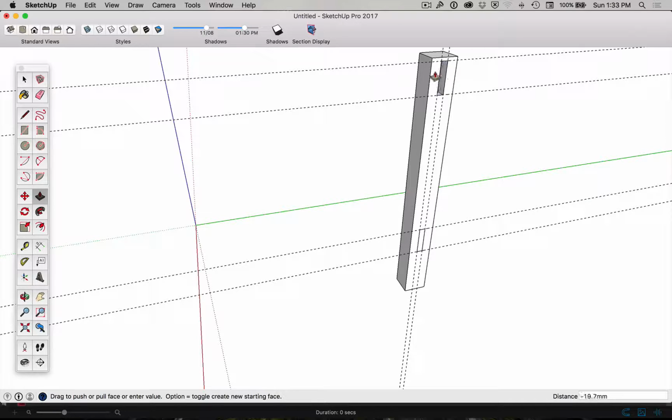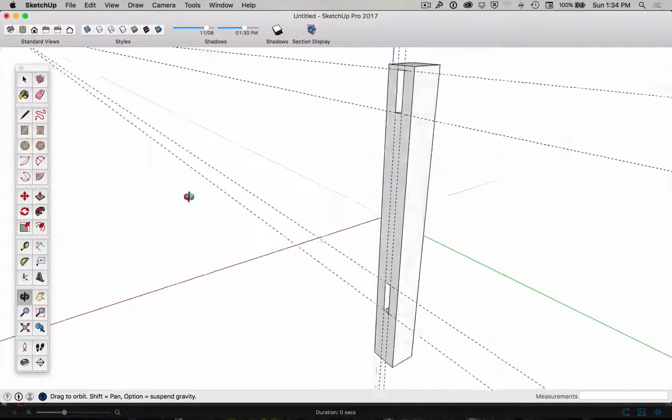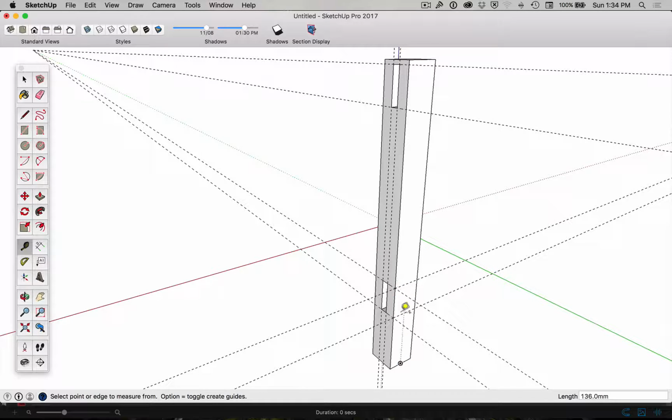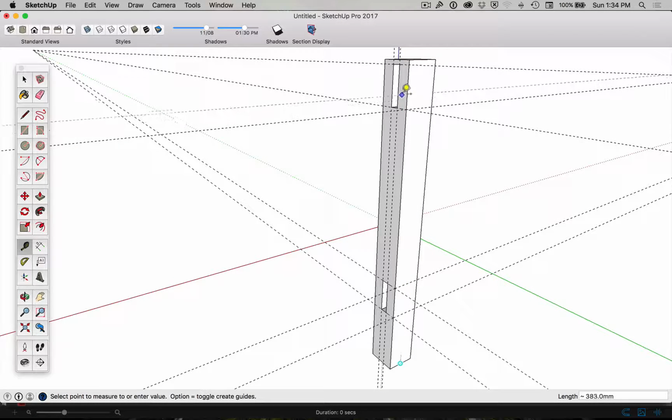Now we said that we're going to push our mortise in, I think about 15mm, and I'll do the same here. And I've got to run another one here. I'm just going for the tape measure. I'll click that up. I might as well just do it to there. See, as it snaps to that line, it makes life pretty quick and easy. Snaps to that line, go up to there. As long as you see that cross, you're pretty sweet.